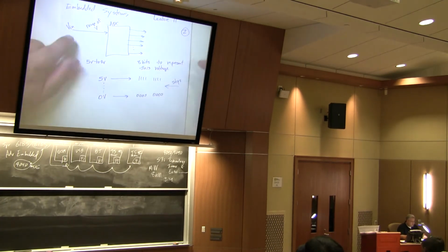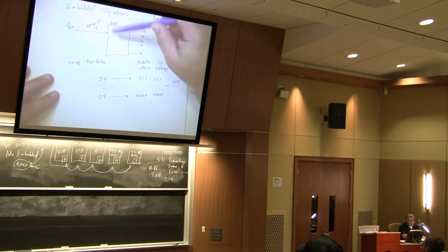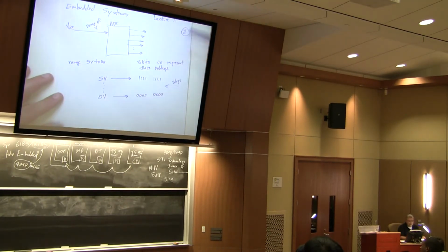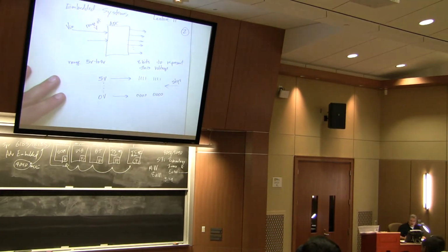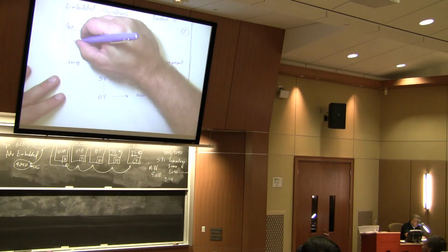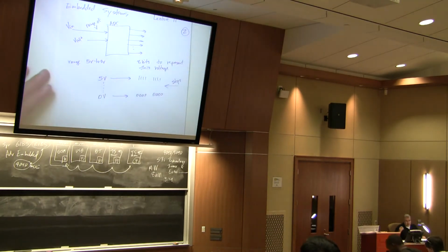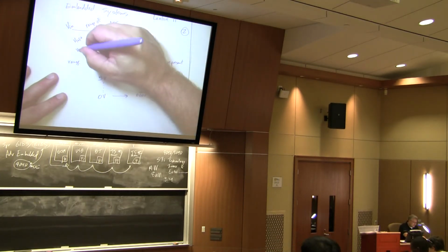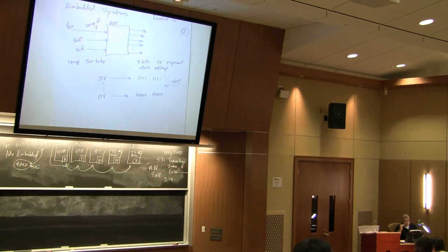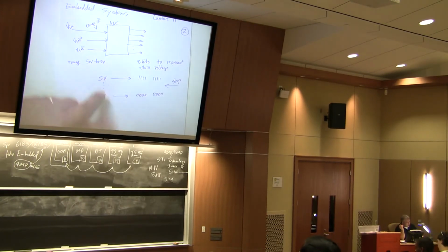Now, do we know what the range of voltages is going to be for this, just as it's drawn? Usually not. So what we need to do is add what we call reference voltages. We need the voltage reference plus, which says this is going to be the highest voltage. And we're going to add a voltage reference minus. That's going to be the minimum voltage that we could ever read on Vin. And that's how we will determine what our upper end and lower end is.